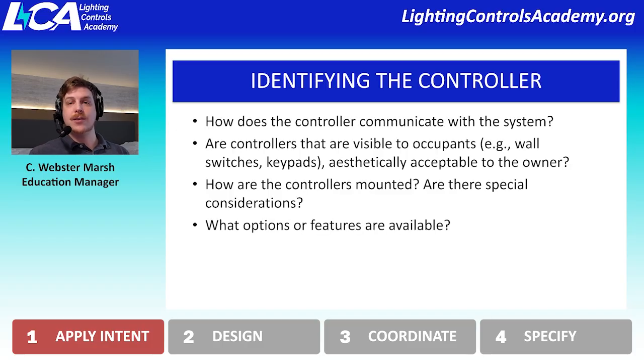And then, are there any additional options or features available for these devices? For instance, if you're trying to do color changing DMX, which is a specific protocol oftentimes used in entertainment and color changing applications, the controller might not actually have the ability to control DMX. So confirming whether a controller has that capability, if you need that capability, will help make sure that the system is going to provide the controllability that you need.